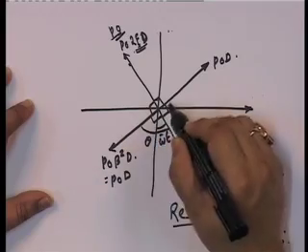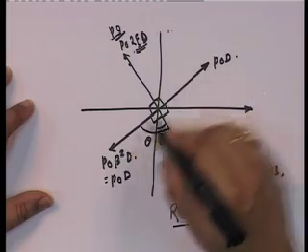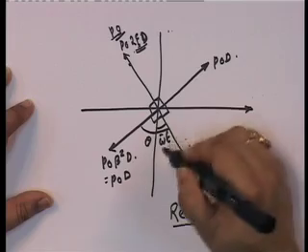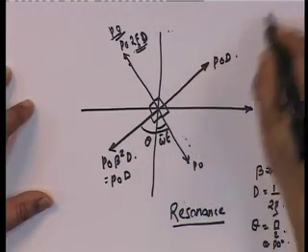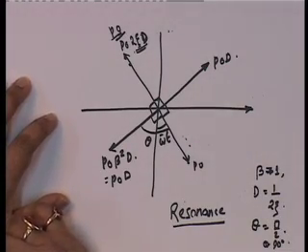They are 90 degrees out of phase with the applied load and the damping force, and they balance each other out. Note that these values will be very large because P naught D is very large. So, you have a peculiar situation at resonance: since the damping force resists the applied load, the inertial force and the elastic force are very large. However, they are 90 degrees out of phase with the applied load. So, despite them being very large, all they do is cancel each other out.